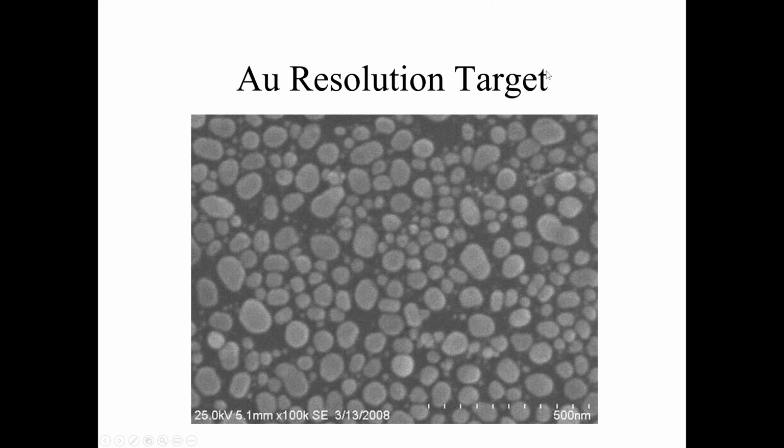Okay, what's the highest you can magnify and resolve on this instrument? The instrument will go from 0 to 300,000. But this is just a field of view. Magnification is just a scanning area ratio with scanning speed. You either have a big number on top or you have a big number on bottom. It doesn't physically enlarge the material. It just changes the field of view.